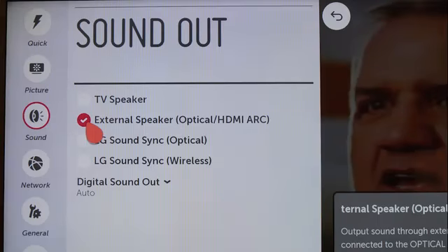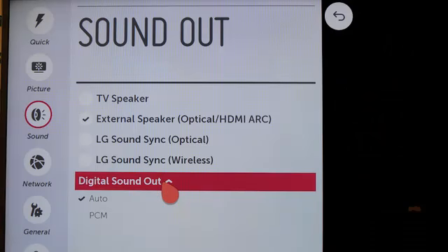Now it's complete, and since you altered this to AC3 on the Easy menu, you have now allowed this TV, when it sees AC3 audio, and you have it set for digital, remember, the output digital for auto, then out of the optical will come whatever particular AC3 Dolby Digital audio there is processing. Now you can have surround sound through your home theater. If they want to convert that back to PCM, they can do that now through the customer's menu and just go in there and change it to PCM only.